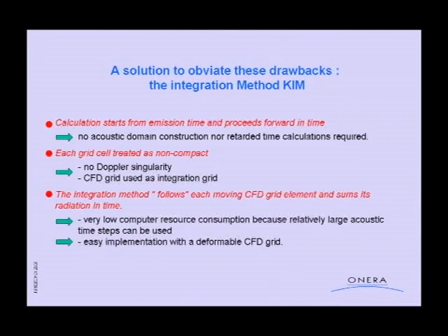The main features of this method are that we start the calculation from emission time and proceed forward in time, so that no acoustic domain construction or retarded time calculation is required. But what is more interesting is that each grid cell is treated as non-compact. That is, we no longer have Doppler singularity, and the CFD grid itself can be used as integration grid.